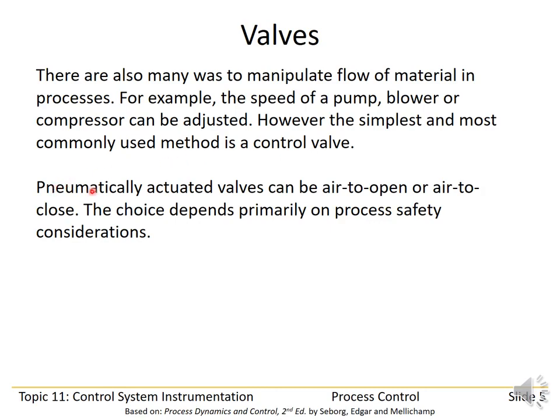As we said, control valves are often pneumatically actuated, and they can be designed to be either air to open or air to close. An air to open valve means that as the air pressure increases, the valve opens. And an air to close valve means as the air pressure increases, the valve closes. And the choice between these two depends primarily on process safety considerations.